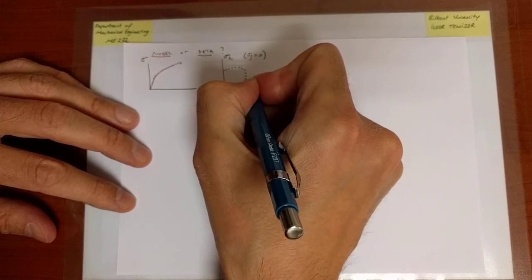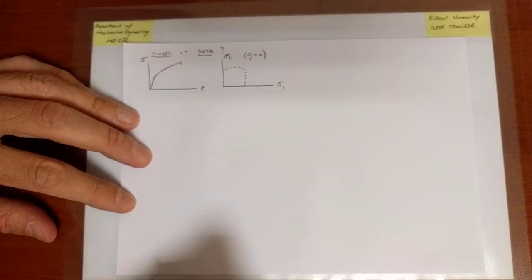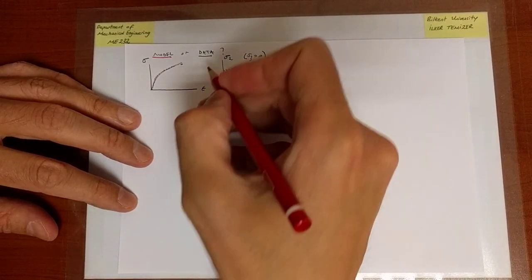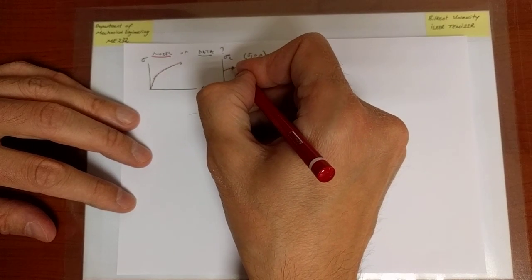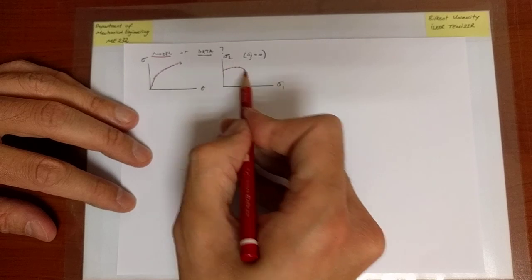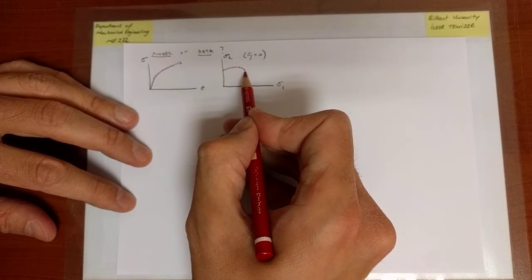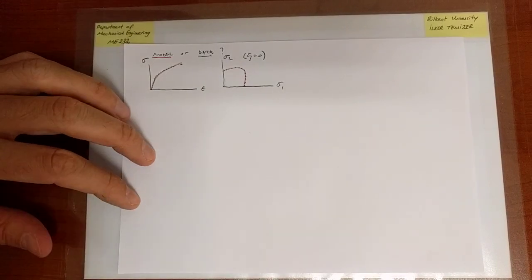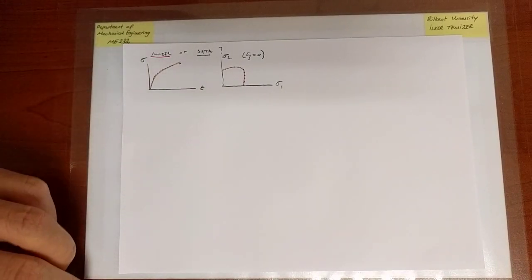And what we've observed is that there can be data which looks like this, and of course we can put a curve through it, which says that the combinations of principal stresses that lead to failure form a line that is essentially, in this case, our model.